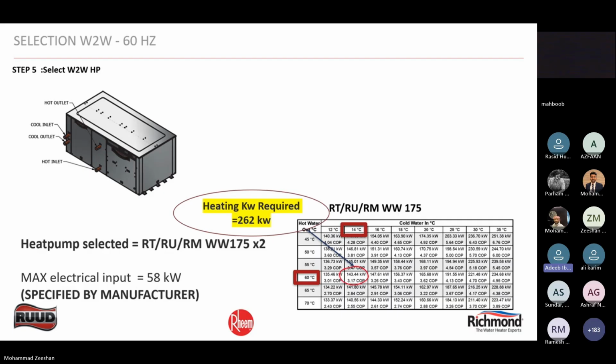I had one question about the water-to-water heat pump. The connection from the air-cooled chiller's chilled water return will connect to the heat pump, so we have 12.7 degrees centigrade. What will be the delta T on the chilled water leaving the heat pump? Roughly between 5.5 and 7.5. So delta T will be 5 to 7 degrees, and you can subtract that value from your inlet.